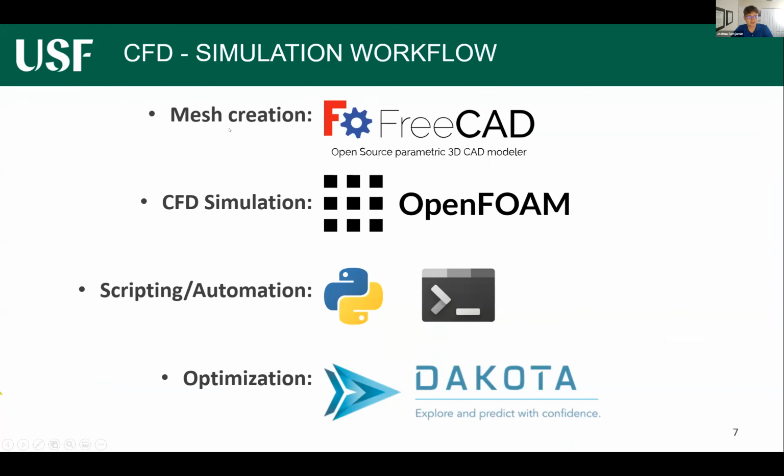In terms of the simulation, we used computational fluid dynamics. And so we were able to create the meshes using FreeCAD. We did the CFD simulations using OpenFOAM. And then we also did some scripting and automation using Python and the command prompt shell script. And we did an optimization for spacer geometry using a software suite called Dakota.